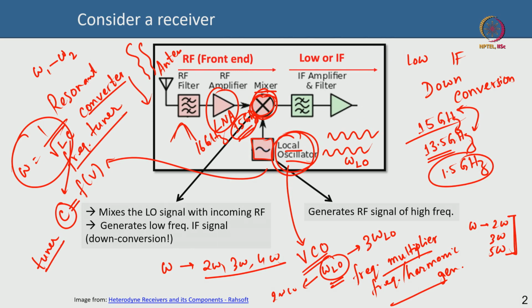You need an element of tunability such that you can tune the frequency by applying a voltage. So it so happens that all of these things can be done by a capacitor whose value changes with voltage, and that is precisely a varactor. Okay. There is also a varistor where you can change the resistor, but here we are talking about a varactor, which is essentially a variable capacitor, a capacitor whose capacitance can be changed by applying a voltage. And if this changes non-linearly, which it does, we will see that, then that non-linear variation of capacitance with respect to voltage will help you generate higher order harmonics, that is useful for frequency multiplication.